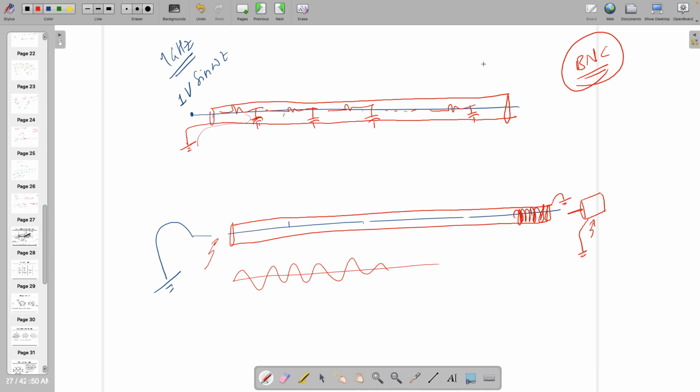If it is a 1x probe in our laboratory, generally it's written 50 ohm in shunt with 1 picofarad. If you go to 10x, it is 1 megaohm in shunt with 1 pico. 100x, 10 megaohm, 10 or 15 pico, something like that.